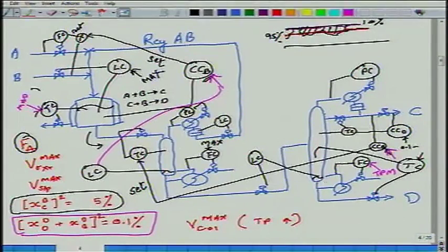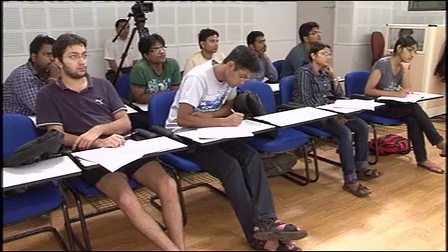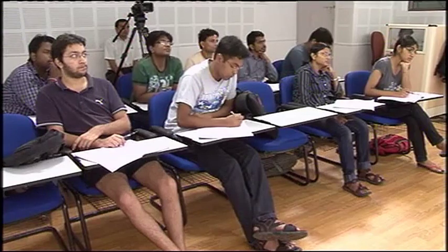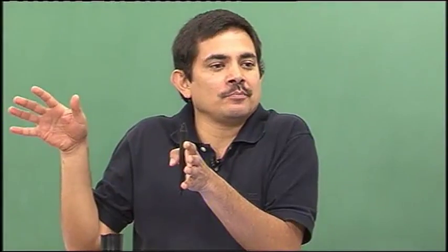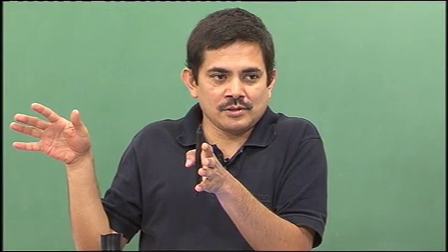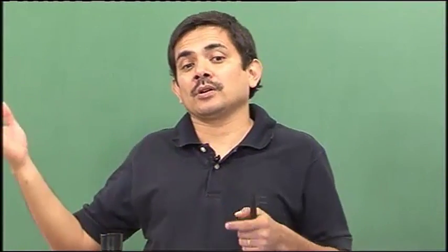If I allow more impurity D in the top, my reflux goes down. If my reflux goes down, my boil up goes down. Yes or no? In a conventional sense, not in this control system, but in a conventional sense. So, from all these arguments, I can say that to maximize production, B should be in very small quantity, D should be the major impurity. Yes or no? Does that make sense? That will give me maximum production.